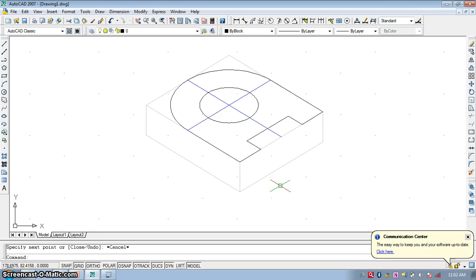So next, you have to just give the thickness for this shape. So I will go to this, and the thickness is 18, right? So I will use the F5 button and just 18. So this side obviously 15 is there, and then just connect it. And then next also having thickness 18, and then this point and this point.